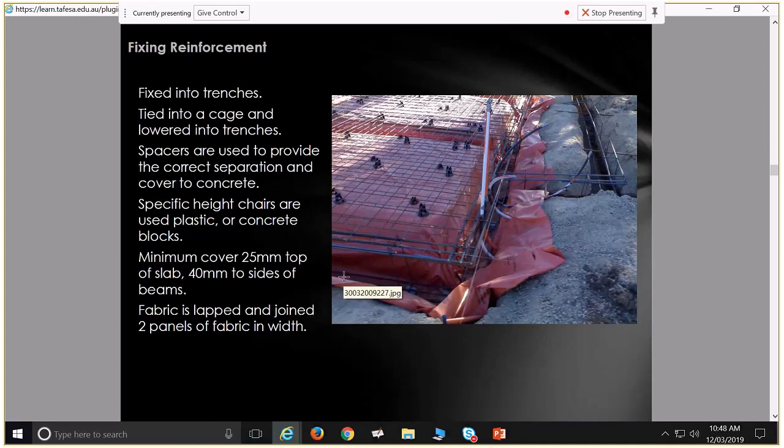This one here is more your typical slab detail that you see for your steel fixing. Probably got 10 or 12mm bars in there. We've got 3 on the bottom, 3 on the top, and then fairly long ligatures holding it all together. Then on top of your steel bars, you've got this mesh which is included. Now that one's got 2 layers of mesh. That's not so normal. But that mesh is to control the expansion and contraction of your slab.